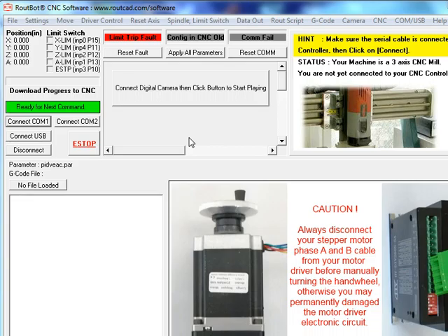In our case, we do not have a COM port on the computer that we have installed the graphical user interface on. We only have a USB port, and this is the case with most modern computers. In this case, we need to use a USB to RS-232 converter. We connect the USB end to the graphical user interface computer, and the RS-232 end we connect to the null modem cable.